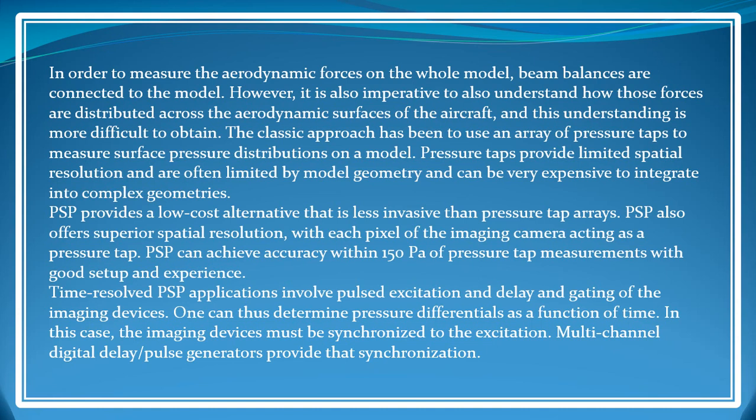We can measure every different pressure at each pressure tap. But in our complex designs, it's very hard to make a pressure tap array, and it's very costly too. But in pressure sensitive paints, we use every pixel of the paint image.